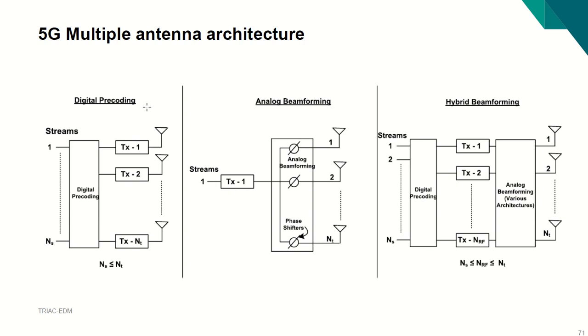By intuition, as you can imagine, if we go up in frequency, we get more losses. As a result, we use multiple antenna systems at the transmitter side and also at the receiver side, so we can enhance or improve the signal.